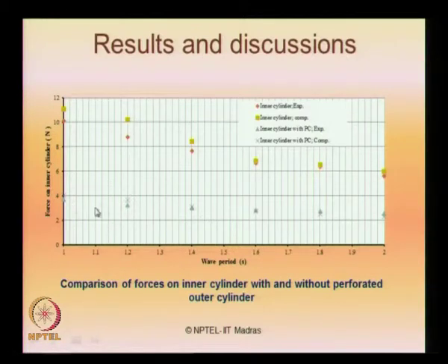And if you look at the results with inner cylinder with perforated cover experimentally, the triangles and the crosses, you will see that even for lower periods the force measured experimentally and the force computed with inner cylinder with perforated cover, which is the idea of the whole experiment, is matching very closely with a very small error of only about 7 to 10%.